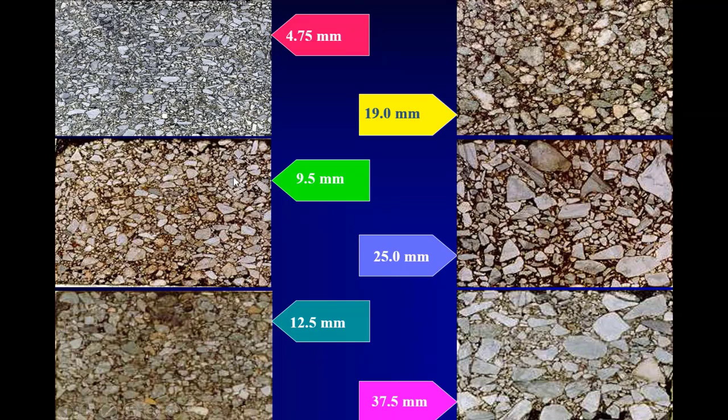More and more now, there's kind of a push. Grand Forks District has done some work on it. There's a push to do these thin lift overlay mixes so that we can keep the lift thickness down and still use conventional paving and compaction. And so I know Kurt Dunn in Grand Forks District has done some work with the Fordville conventionally produced aggregate materials to develop a 9.5 millimeter Superpave mix for North Dakota.